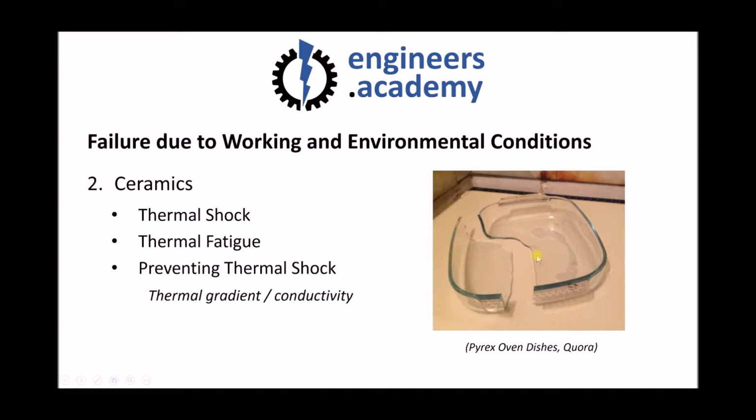But if we were to take that dish and place it in cold water, then the surface cools rapidly, whilst the inside of the material is still hot. So the outside is cooling and trying to contract, whereas the inside is hot and is remaining expanded, and this causes the stresses that eventually lead the material to crack and fail. So one way to prevent thermal shock is to cool the component gradually rather than suddenly.